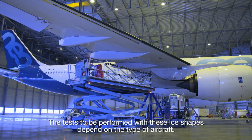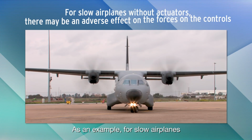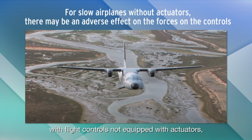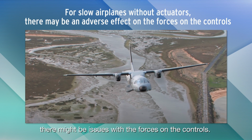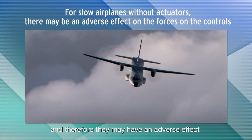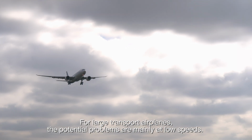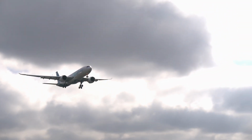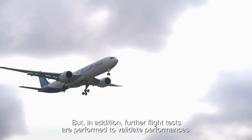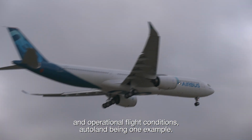The tests to be performed with these ice shapes depend on the type of aircraft. As an example, for slow airplanes with flight controls not equipped with actuators, there might be issues with the forces on the controls. The ice shapes modify the airflow, and therefore they may have an adverse effect on the handling in the entire flight domain. For large transport airplanes, the potential problems are mainly at low speeds. But in addition, further flight tests are performed to validate performances and operational flight conditions, autoland being one example.